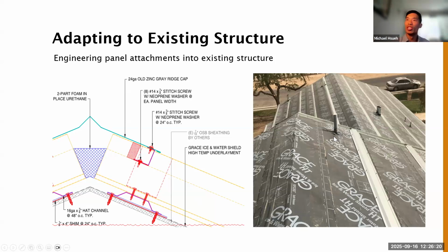But because we're dealing with an existing building, they assumed that they could just fasten right into it and use the sheathing for uplift resistance for these panels. The wind's blowing, it's pulling it up. We needed to have them demonstrate to us, hey, calculate what your actual wind uplift is with these panels. Can you just fasten into the sheathing? And the answer was no, you could not.